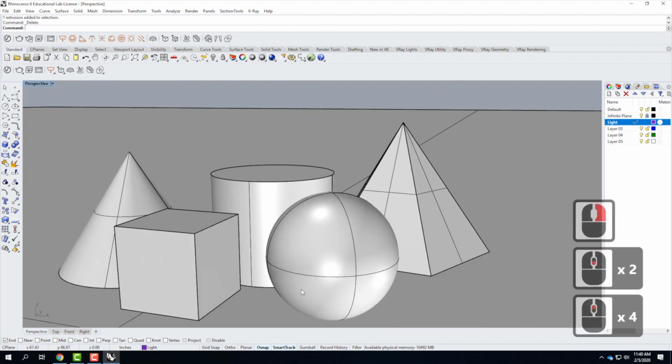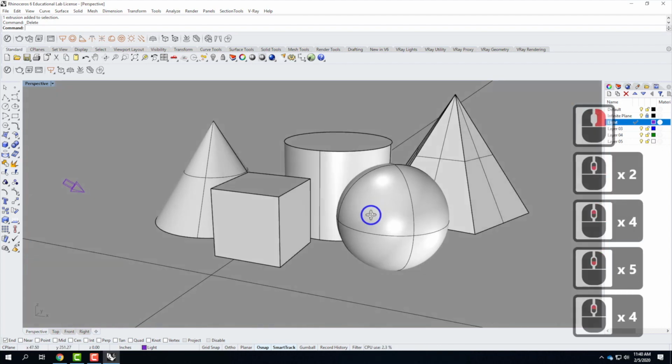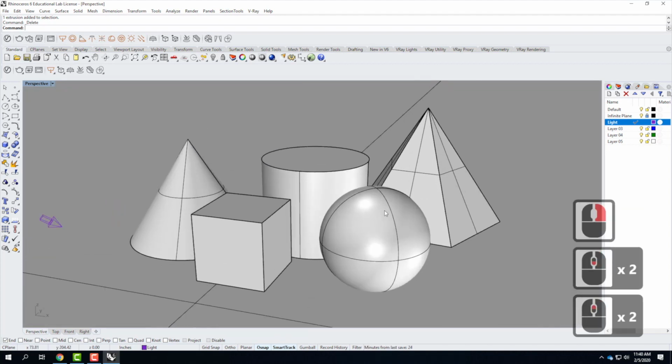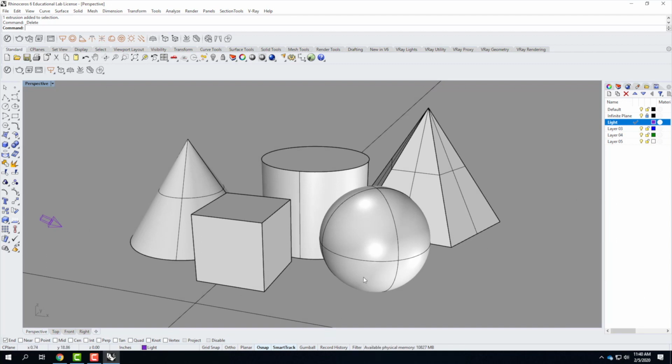So I now have that set up. And so I'm going to zoom in here and get my scene set up the way I want it. I can choose how much of a perspective I want to be looking at it in. We'll say something about like that. The next part is, because I'm doing renderings, and this is something I'm going to emphasize over and over in the course, before you perform a rendering, I want you to save the view so that you can go back and re-render in the same view. What this does is it allows you to make changes to the rendering, change your materials, change how the materials look, what the texture mapping looks like, or whatever, and you can always come back to the same rendering and re-render that render over and over.